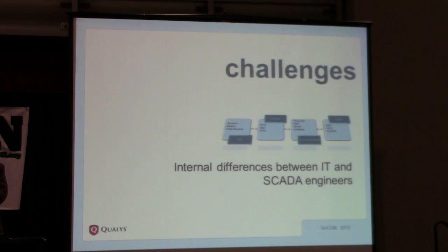And then the SCADA team says, okay, you are never going to scan or do any audits on my system. And that happens more often. So if you are on the team which tries to secure the system, please talk with your SCADA people first and try to get a window where it's okay if something goes down, because more or less when you scan a SCADA system, something will go down.